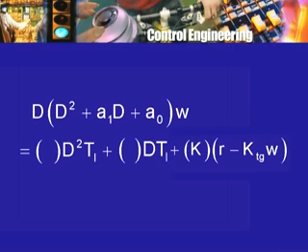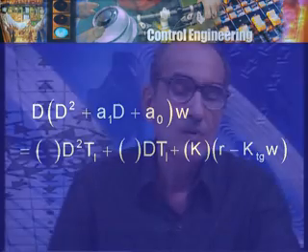The root locus method can be looked upon as a method for finding out the variation of the roots of a polynomial whose coefficients depend on a parameter in a linear fashion. So, we can see here that there is going to be some effect, and what the effect will be, of course, will require a study of the cubic polynomial and how changing its constant term in the cubic polynomial is going to change the roots. So, this is an example of a time domain approach where we have used a method of elimination to get rid of all the variables except one of interest.